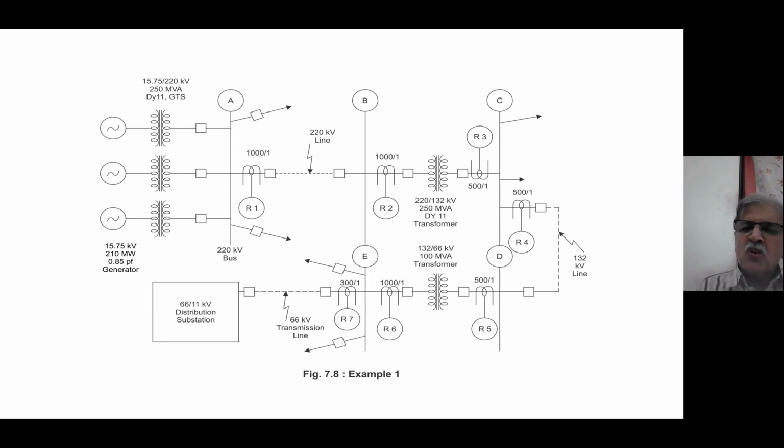We consider normal relay error, breaker error, overshoot, etc., I consider 0.25 second discrimination margin. That is a discriminatory figure. Many research paper writers are considering 0.2. Some of the research paper writers consider 0.15 also. But I am, you see, considering 0.25 second.